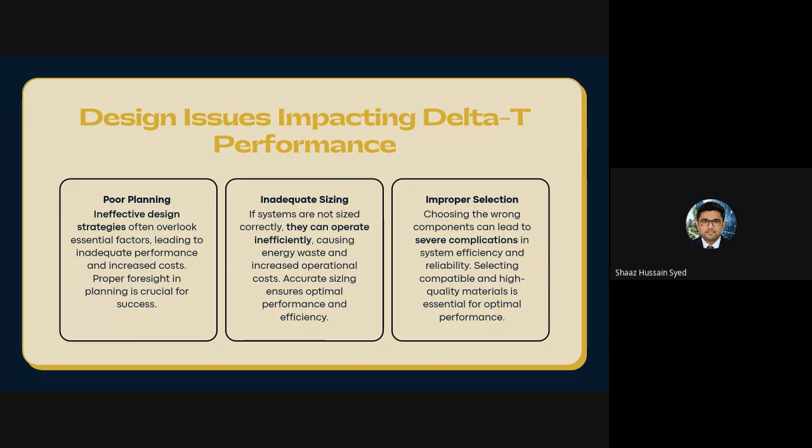Sometimes due to the use of three-way valves, the bypass coil is open and the water will circulate easily, which is also a reason for delta T collapse. And if you're using low valve authority, the weak valve cannot control the water properly, so too much water flows through the valves and not enough heat is absorbed. This also is a reason.